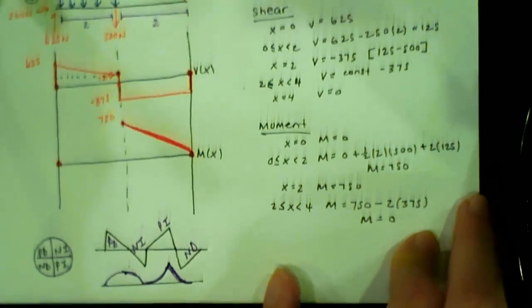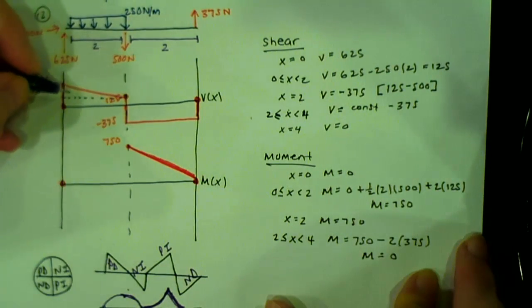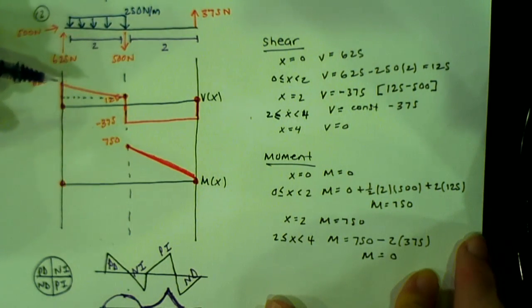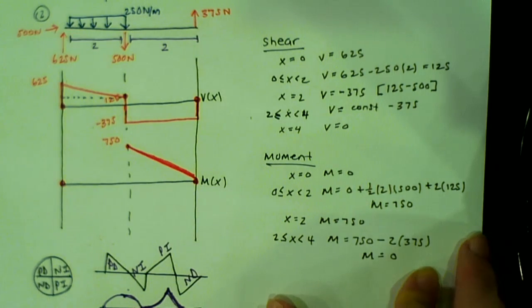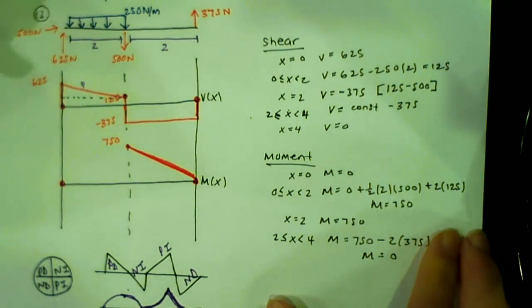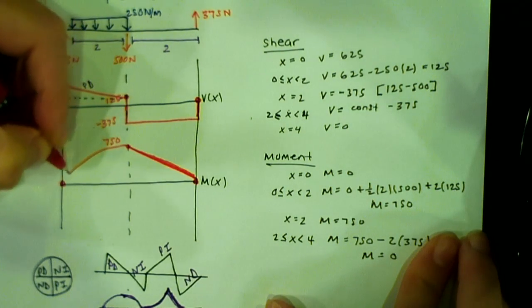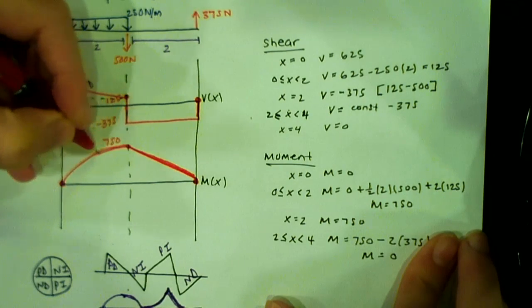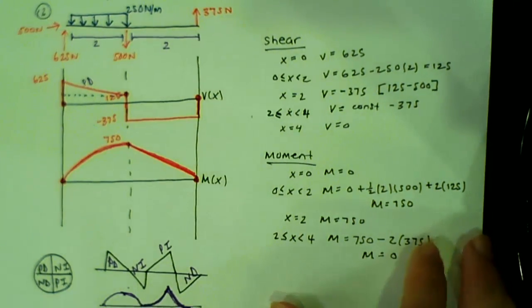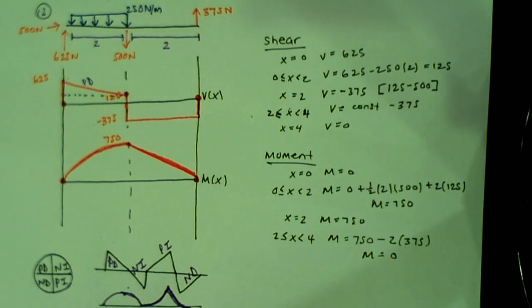So if I come back to our problem here, is this shape right here, for my shear, positive or negative? Is it increasing or decreasing? So that's positive, decreasing. Therefore, our shape looks like that. So for the most part, I always use this method of areas.